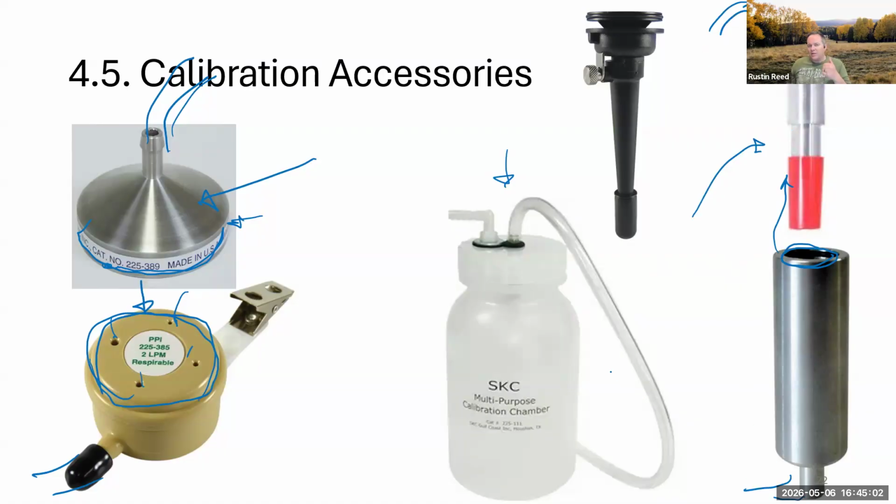So it's always the adapter goes to our calibrator, and our media, our filter, our sampling media, or let's say calibration media, is going to the pump. So just like when we sample, our media goes to the pump. Well, when we calibrate, media is connected to the pump, adapter connected to the calibrator.